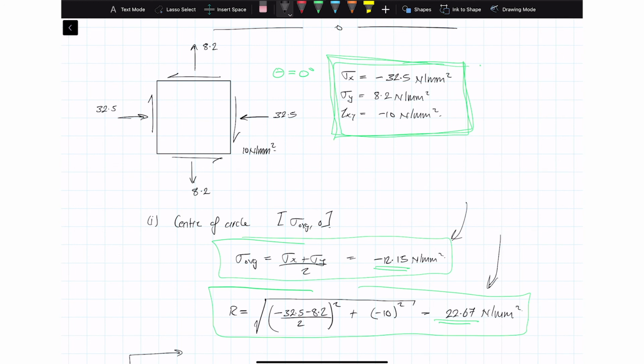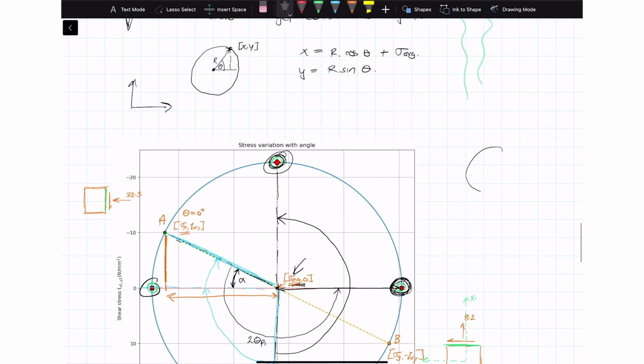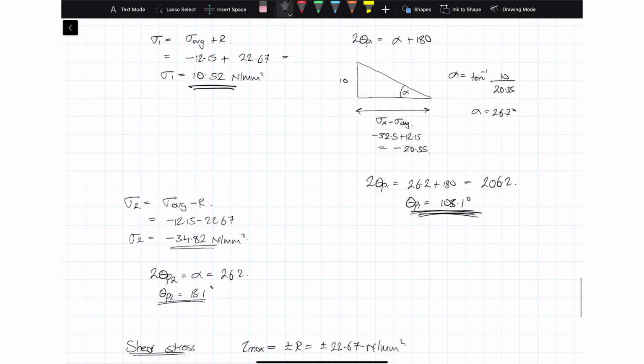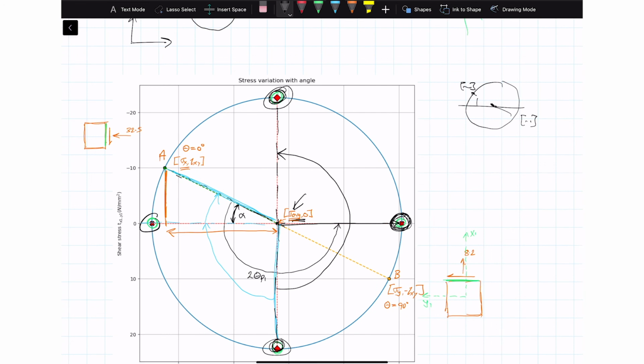Now, everything we've done up until this point, I would say, is really just in service of getting us to this point, right? I personally wouldn't try to remember the transformation equations and actually execute those transformation equations. If I had to address something like this practically, I would go straight for a more circular approach. I would work out my average stress, I'd work out my radius, I'd do a little hand sketch of my circle, I'd approximate where the point is somewhere there, I'd have coordinates for that, then I know that I have another point down here, I'd have coordinates for that, and then I would be able to do everything that you saw me do here, all very basic equations. Instead of having a nice, well-plotted version of Mohr circle, you can do all the very same thing on just a hand sketch of Mohr circle.